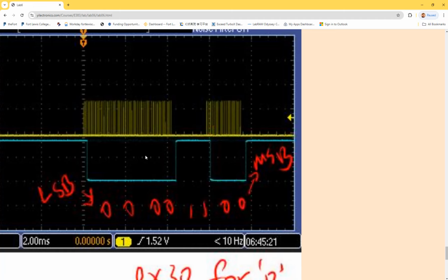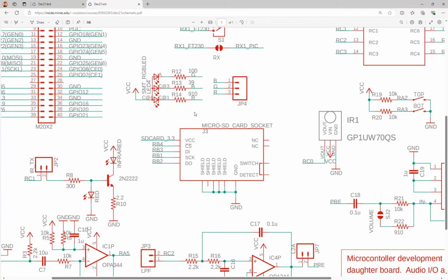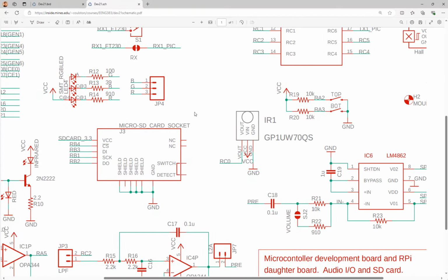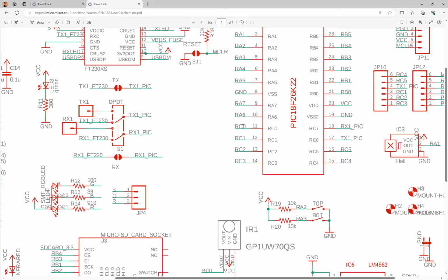And then this data comes in, right? And this data is being sent to the UART port. Now let me ask you this question, okay? Let's make sure you guys understand it. So this signal arrives where? RC0. RC0 is where? It connects to RC0 of the chip, right? Microcontroller? Yeah, my controller. Is it reading or output? Reading. So whatever you hear will be read into here. Okay. Then what?